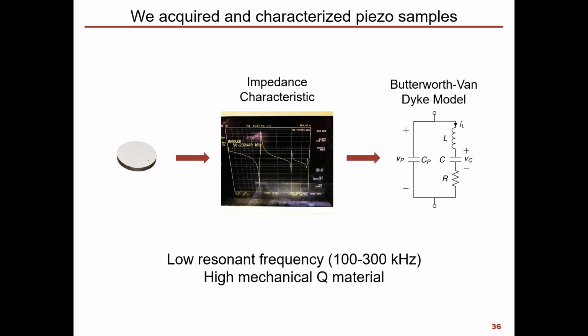What's interesting about this, and it is difficult to explain sometimes because we're so used to thinking that resistance is what we need to be low, is that we are actually interested in the ratio between the characteristic impedance of the resonance and that resistance.